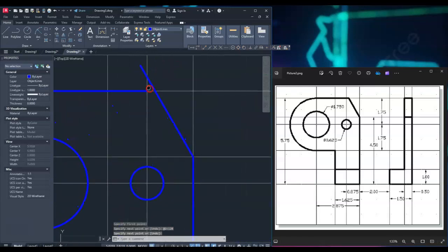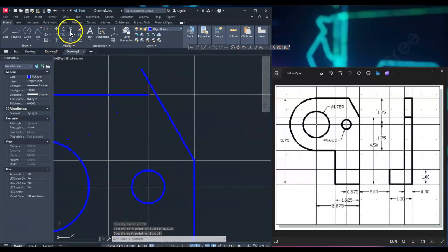And then here I've got a bit of a gap. So what I'm going to do is extend. I'm going to go over to my trim, change this to extend. It says select the object to extend, and automatically it's just going to preview extending over to that line. Now I can switch back to trim, and then trim off this excess line piece here.